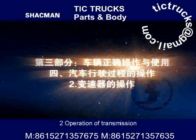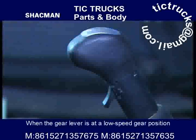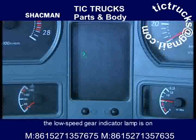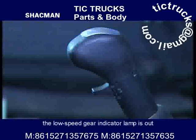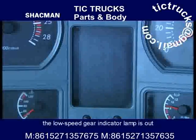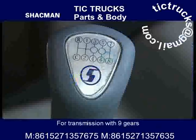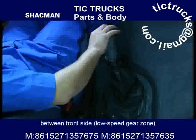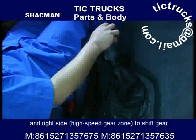2. Operation of transmission. Gear position of transmission. When the gear lever is at low-speed gear position, the low-speed gear indicator lamp is on. When the gear lever is at high-speed gear position, the low-speed gear indicator lamp is out. Shifting between high and low-speed gear zones. For transmission with 9 gears, you can pull or push the gear lever between front side, the low-speed gear zone, and right side, the high-speed gear zone to shift gear.